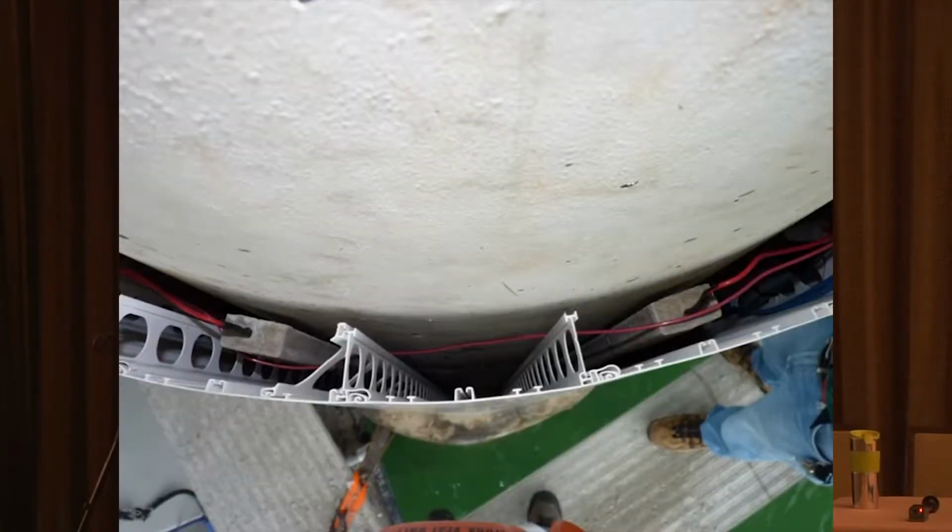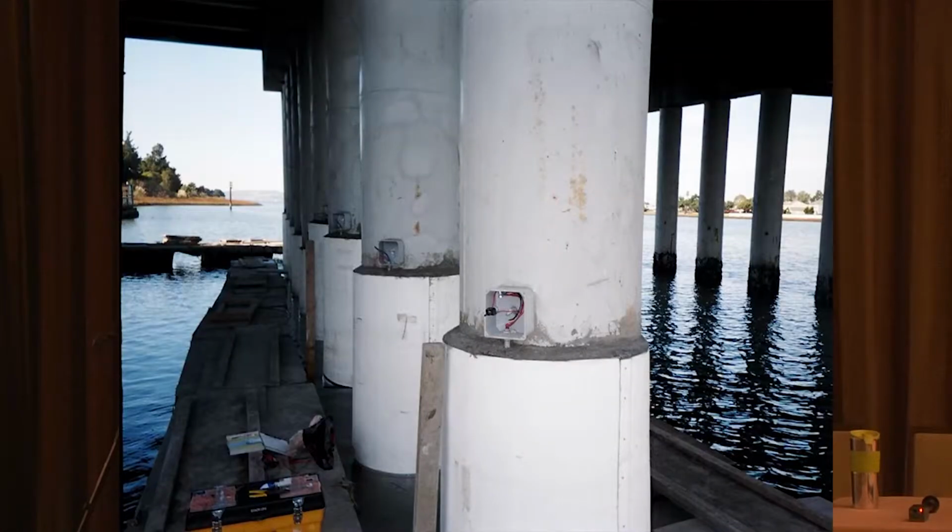There's a spacer system on it, and if you look here too, you'll see that these are the anodes that are wired together and attached. This is where they are right here, wired together, attached to the underlying reinforcing steel. This is prior to a grout system being placed to encapsulate the whole system. This is what it looks like after the fact. This is a project in California, in San Leandro. It was done a number of years ago. And you'll notice that there are some junction boxes at the top of this that are used for monitoring the performance of the system.